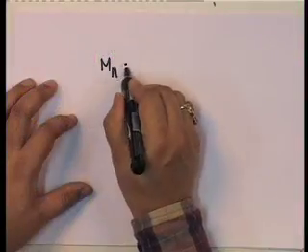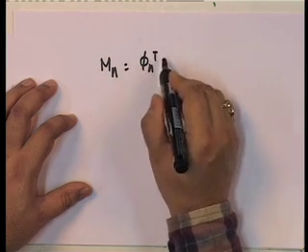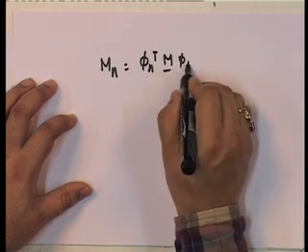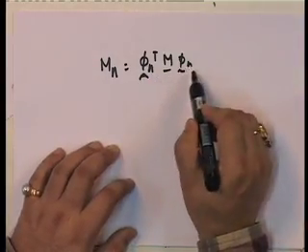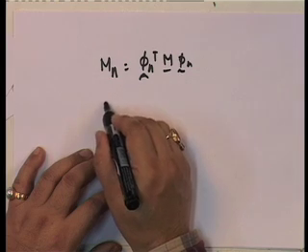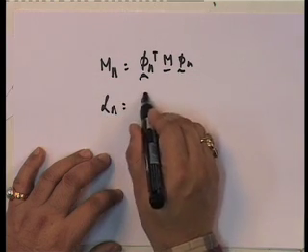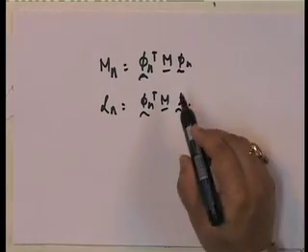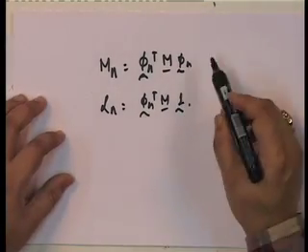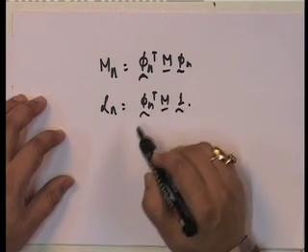This is very interesting. See why I did the generalized single degree of freedom. If you look at m n, it is equal to phi n transpose m phi n. In a way, you can look at this, this is like the two together, and Ln is equal to phi n transpose m into 1. Do you see the correspondence with the generalized single degree of freedom? There, what did we have?